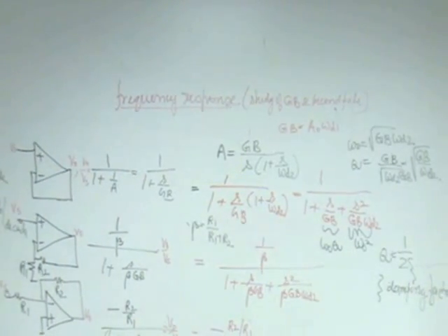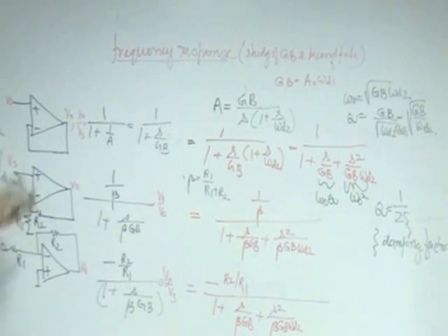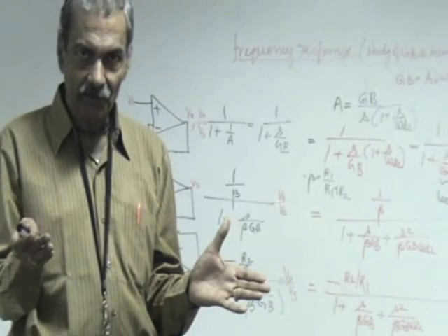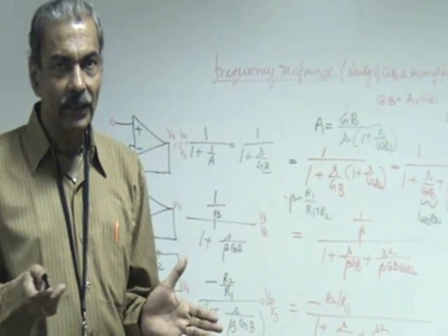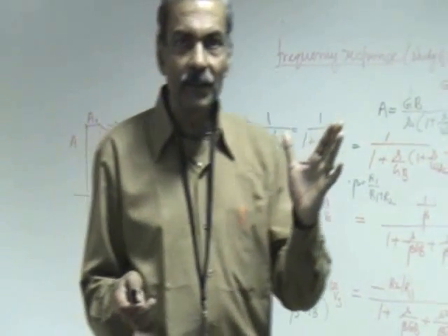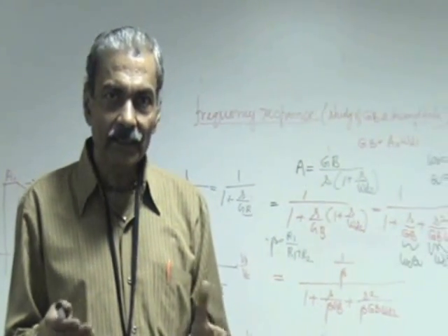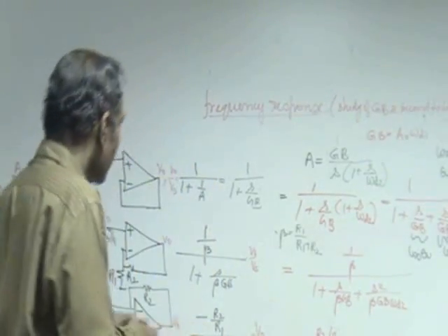Further, we have the time response to be understood. In time response, if you give a square wave for a unity gain amplifier, a square wave of the same amplitude is supposed to appear at the output. However, it gives us a rate of rise which is not abrupt but controlled by the maximum rate at which output of the op-amp can rise, and that is called slew rate.